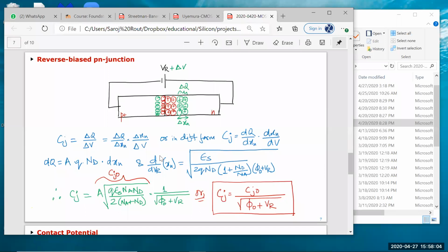And we calculated this nonlinear capacitor because basically we said it looks like a capacitor, which adds delta Q to the plates, but it increases the distance. Unlike a linear capacitor where the distance always remains constant, you're just adding charge if you increase the voltage. Here you're adding charge and increasing the distance as well. So effectively, because the capacitance is epsilon by Tox, effectively this looks like as if the capacitance is decreasing as we are increasing the voltage.